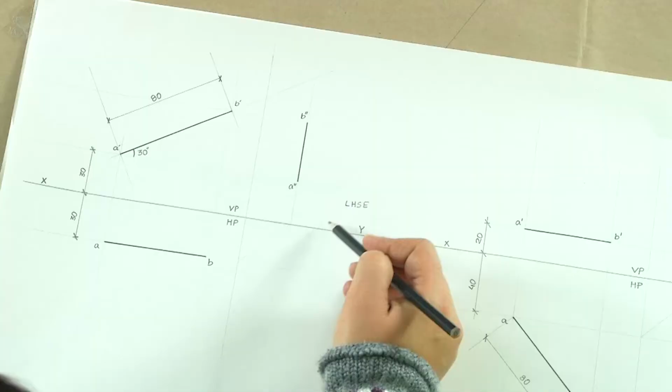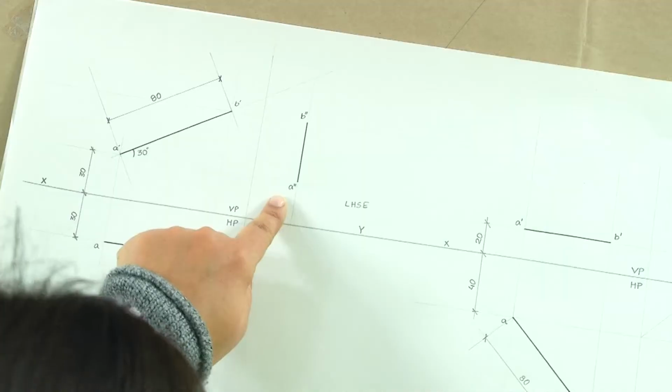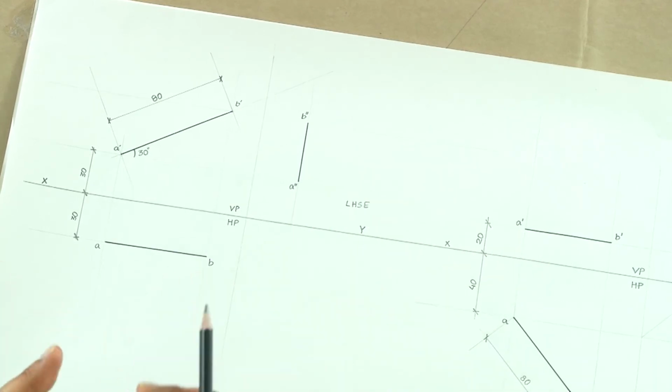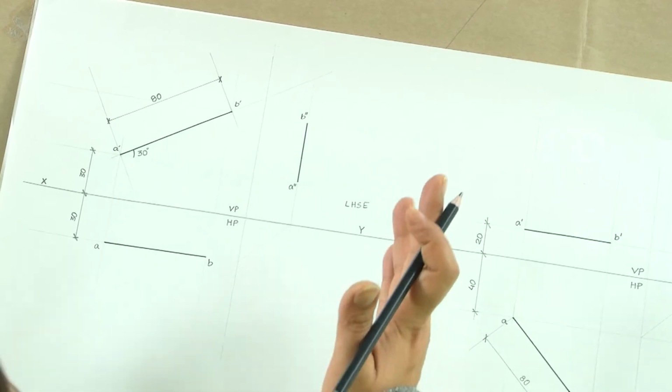Another thing that you have to keep in mind is the font size. The labeling of the sheet has to be appropriate, of appropriate size. If the font size is too big, then that will dominate. If the font size is too small, then it will not be readable. So, we have to have a balance between what size of font will be used. It has to be just proportionate to make your drawing look good, and then the drawing has to be distinct.